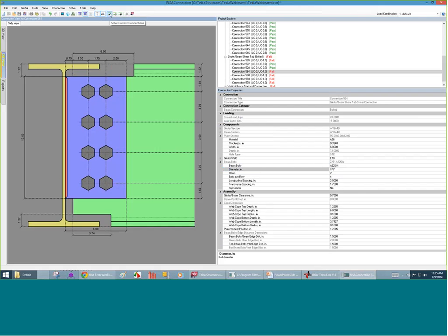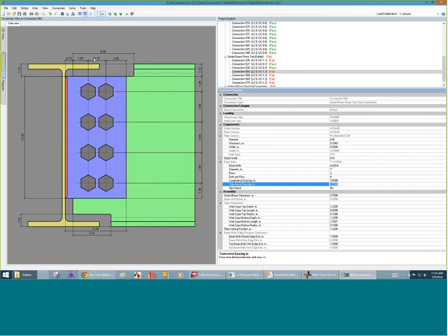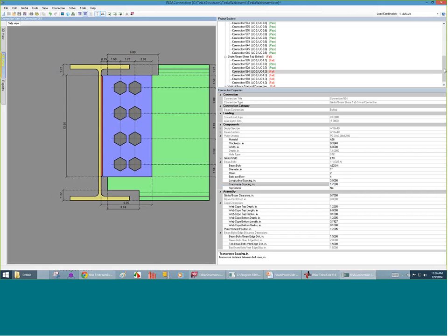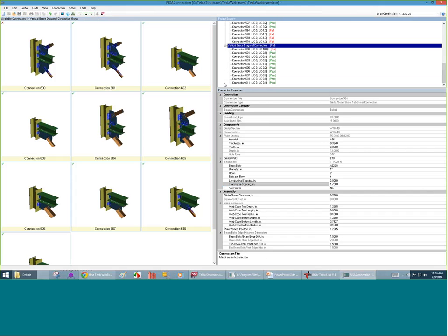So what's going to make this connection better? And what's worth it to me for construction? Do I need to continue to add bolts? Do I just say, hey, I probably need to make this a different connection type? And if you do, then what you can do is move that over to Tekla, back in the Tekla Structures model, and reassign it. Maybe this just isn't an adequate type of connection. So you can walk through all those different design decisions as you go.